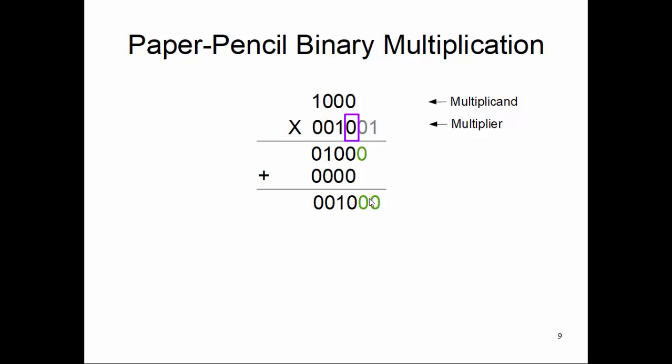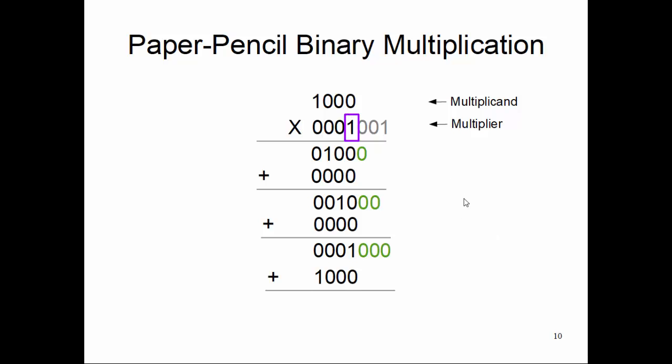See, we are finalizing that 0, one more bit, and then the partial product shifts. Then we finalize 3 of the bits, 0, 0, 1, and then at that point we add the partial product and shift. Now we got our result, 0, 1, 0, 0, 1, 0, 0, 0. And that too we achieved by adding up only 4 bits at a time. We no longer need 8-bit addition, we need only 4-bit addition.